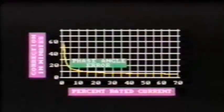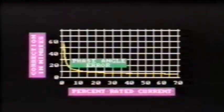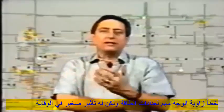And here is the correction factor for phase angle. The correction is shown in minutes of a degree. You can see that the error is very small, less than 1 degree. The phase angle error is important in revenue metering, but it really has little effect on relay performance.